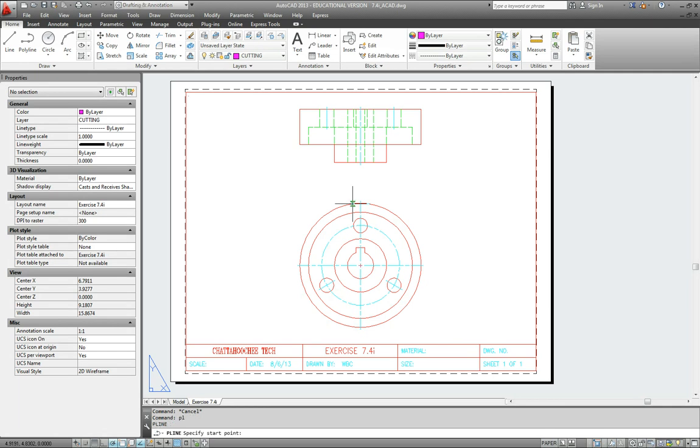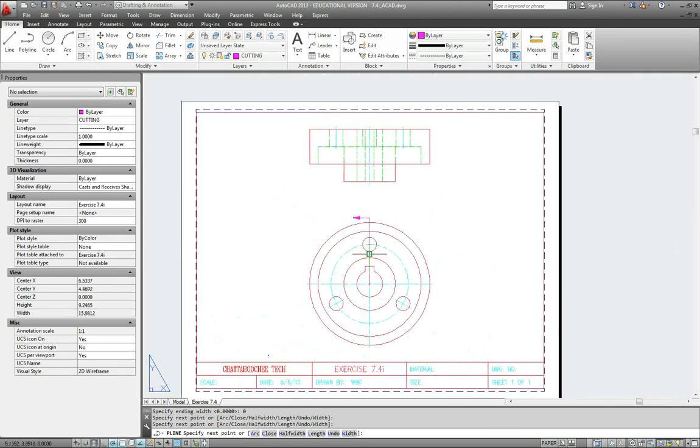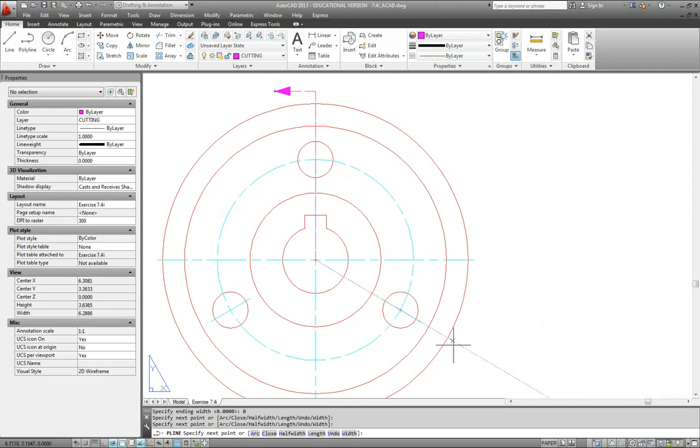So polyline, I'll start in here, go to the right, adjust my width. Starting width will be 0, ending width will be 0.1, and the arrowhead will be 0.175 long. Readjust, starting width 0, ending width 0, and have my horizontal and vertical lines. Then go to the center, and then go out through here. As you can see in your text, I'll go to approximately this point,